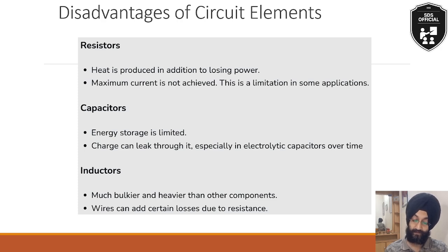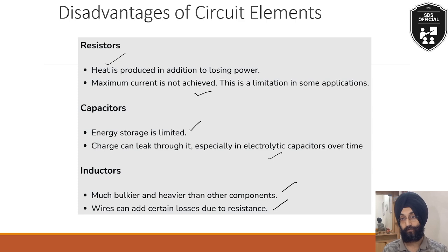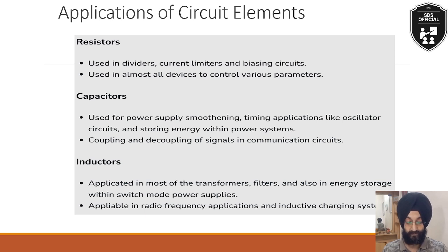So these are some disadvantages. Inductors usually heat up when they are used for a long time, and maximum current is not always achieved. For capacitors, the storage of energy is limited depending on the capability of storing the electrical charge. Charge can also leak if they are not used over time. Inductors are manufactured from coils of wire, so they are bulky. Wires can also have internal resistance along with the inductance or inductive impedance, so they can offer hindrance to the flow of current also. These are the disadvantages.